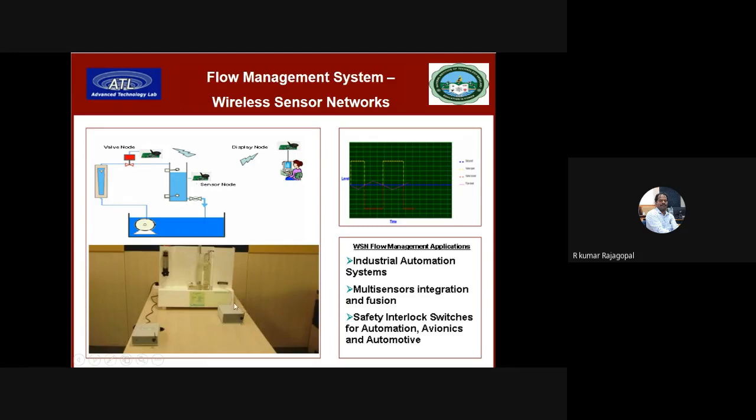So it is based on the turnaround time. So a number of sensors can be connected here. A number of valves or actuators can be connected with one node based on the field environment, in the case of automation. So completely, whatever information is transmitted here for one valve is available here. Similarly, the information will be captured in the display node.